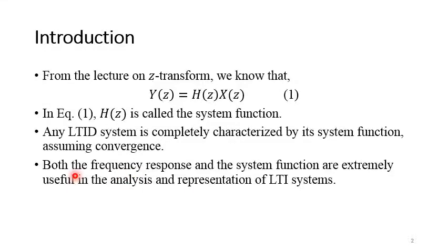Now, further into the topic, we can find the frequency response by taking the Fourier transform of the impulse response. Taking the Fourier transform of the impulse response will result in the frequency response.